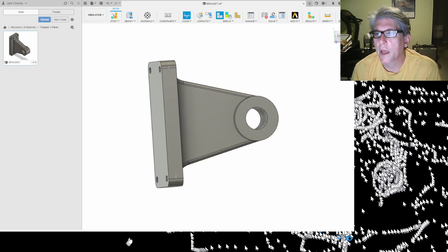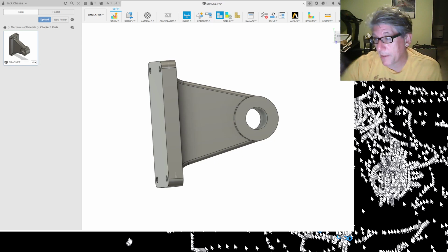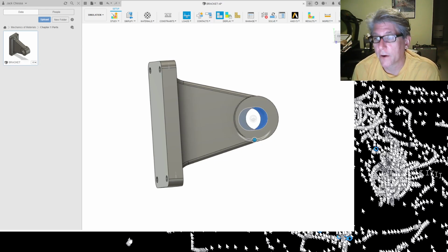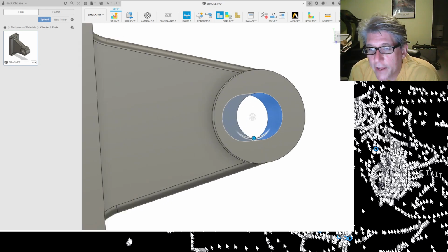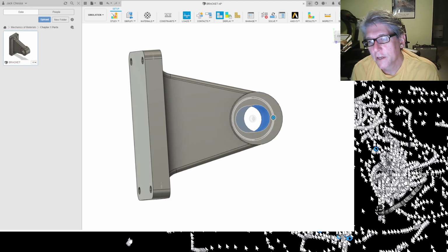So we're going to pick loads, and you can see here different types. One of them is a bearing load. What that will do is put a pressure distribution along 180 degrees of this contact surface, like the upper half of this cone. It won't put any pressure on the bottom, so it's as if the pin is being pulled. Okay, so we're going to pick the surface. Now, that icon's a little small, but if you look at it, you see it's got the arrows drawn as the force is being applied. It'll put a distribution on there, but the total magnitude will equal the magnitude you apply. It's actually acting in this lateral direction, so we want to swing it over 90 degrees so that the force is actually pulling the bracket. And then we want to change the value.